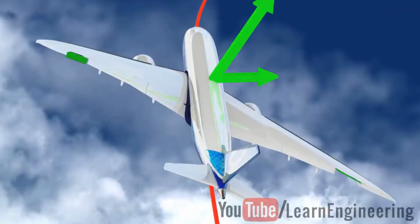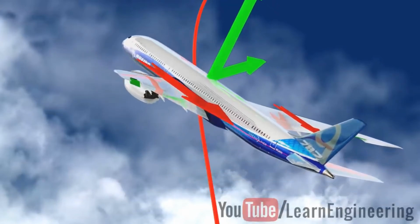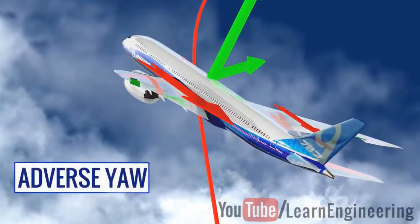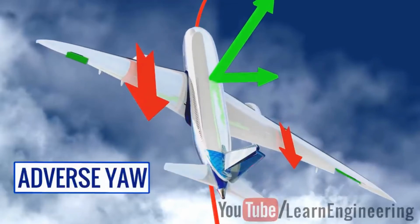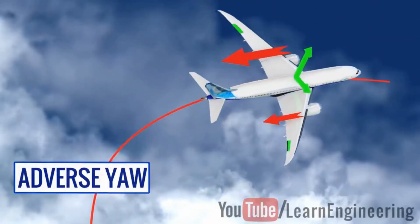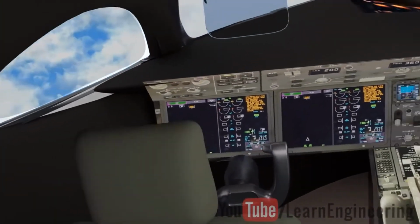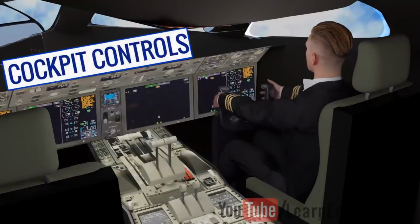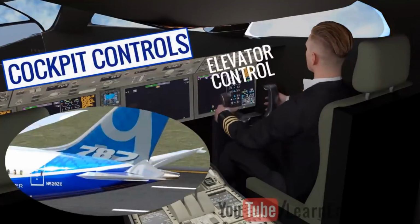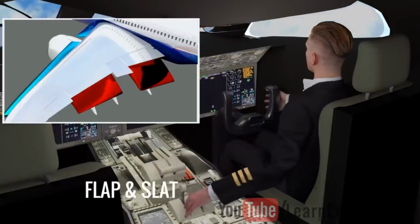However, this banking technique has some drawbacks. When you keep one aileron up and the other aileron down, the drag forces induced on the wings are not the same. This will cause the airplane to yaw. This phenomenon is known as adverse yaw. The rudder has to be operated simultaneously to prevent the adverse yaw. The way pilots control the different wing attachments and the whole airplane is illustrated in this animation. In practice, a control computer accurately manages all these wing attachments using a fly-by-wire system.